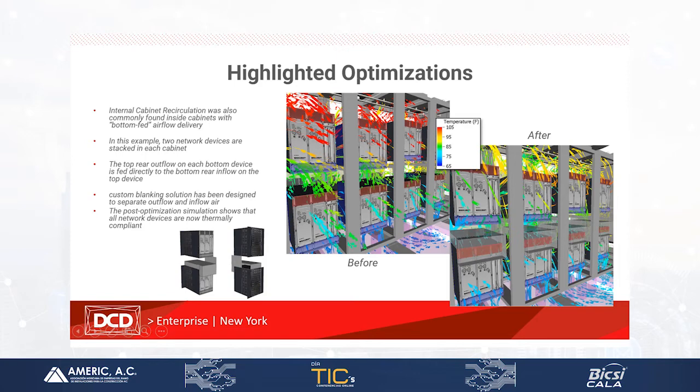where after installing the custom blanking solutions, inlet temperatures dropped significantly to the IT equipment, which increased resilience of the IT equipment, and also allowed them to raise chilled water set points and raise air temperatures to save on energy, and also to make more airflow available to be used by future IT equipment.